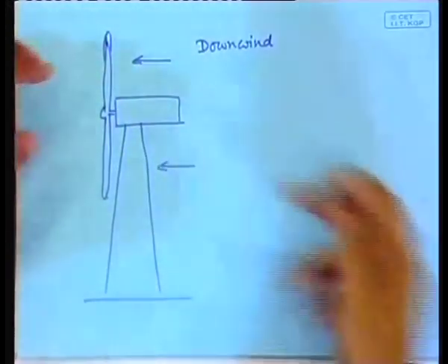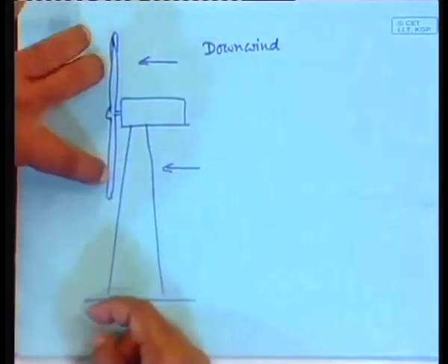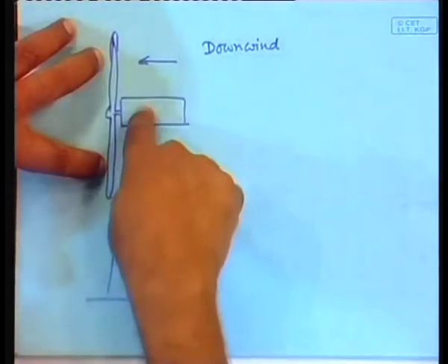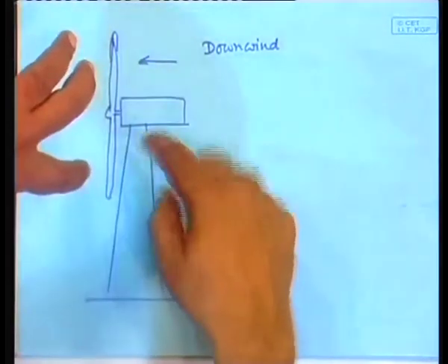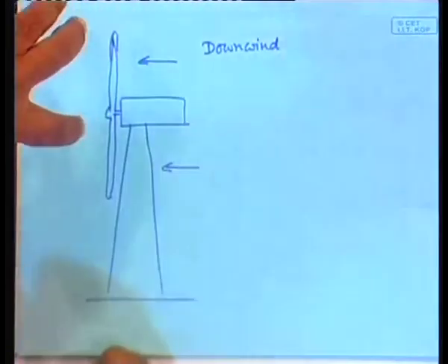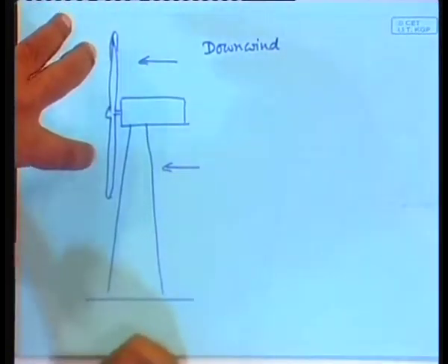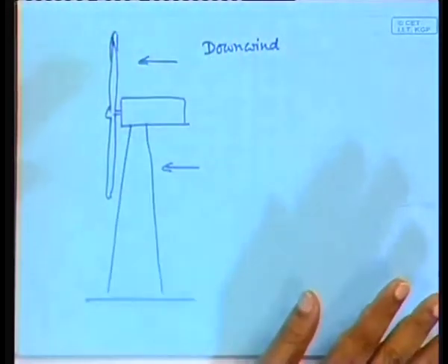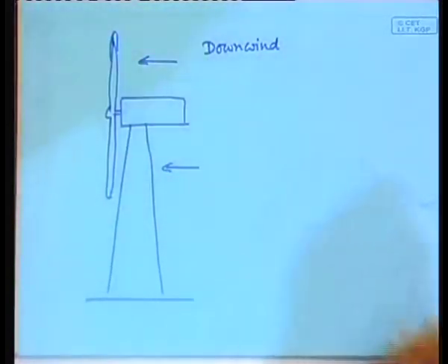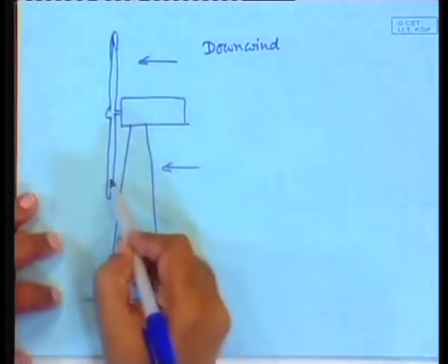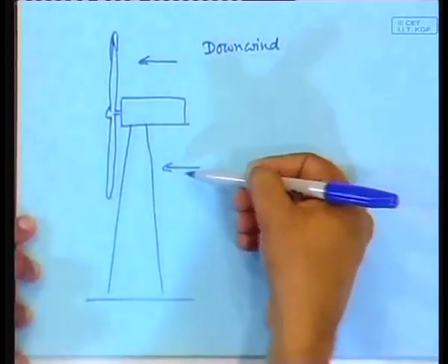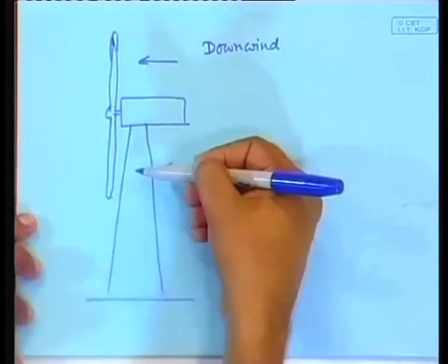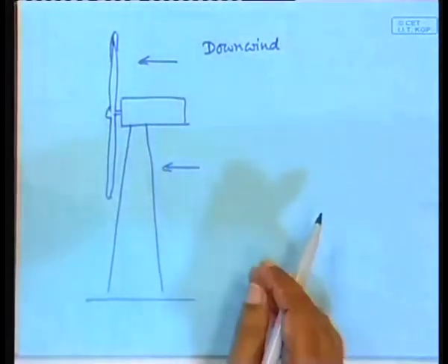Can you see that? The thrust force will act on the blade and the pivot is here. So if it is disoriented, the thrust force itself will orient it back, right? So, if you have a downwind wind turbine, you do not need a yaw control, but the disadvantage is that the tower shadow effect will be larger, because the tower will produce a blockade in one position of the blade. So, that will produce a torque pulsation.